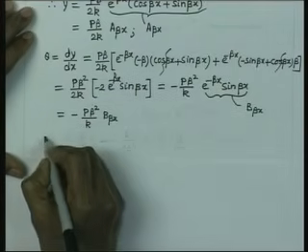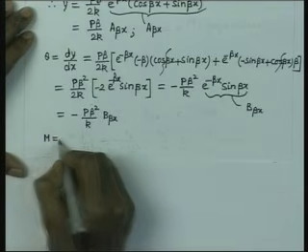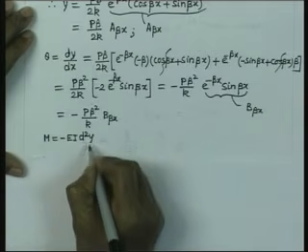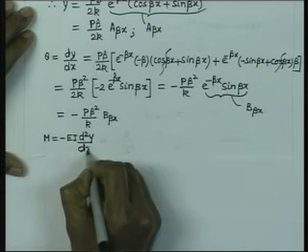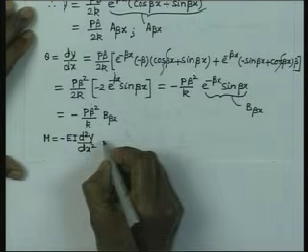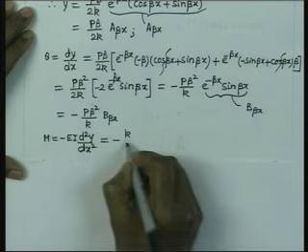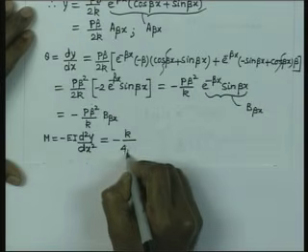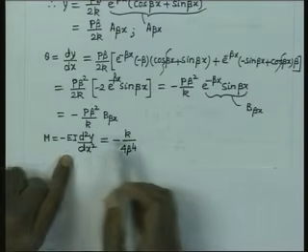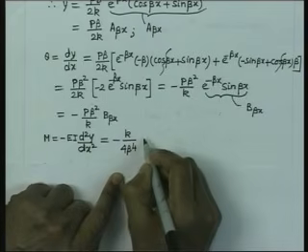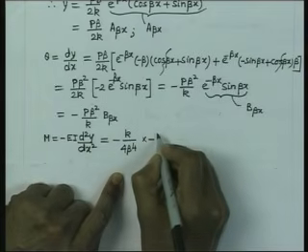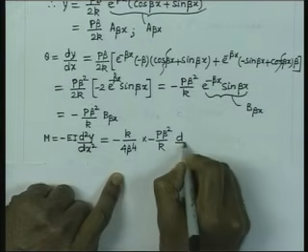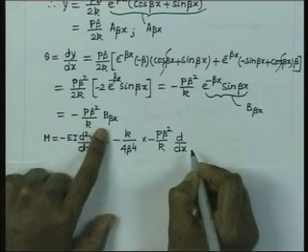Now, bending moment. We can write the bending moment M as EI d2y by dx square, and therefore it means that you have to differentiate. We can write EI as k by 4 beta raised to the power 4, since k and beta are related to EI. So we substitute that into minus p beta square by k times the differentiation of this expression.